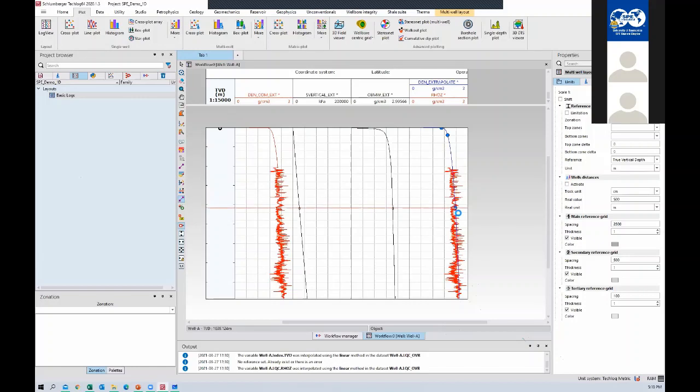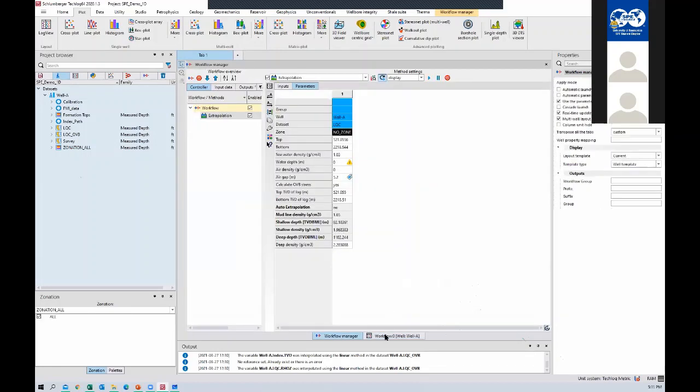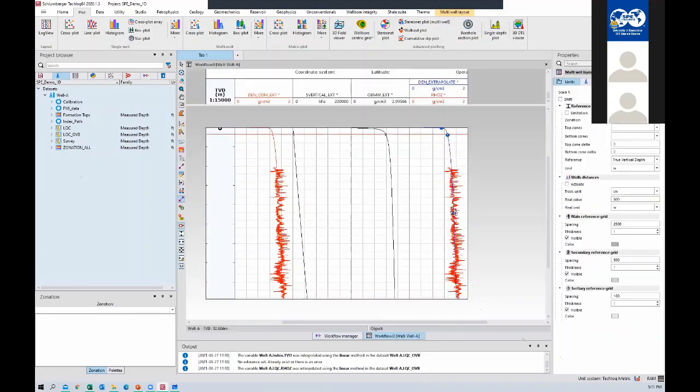Great. So that's how you estimate overburden stress. Once I finalize the parameters and know the trend, the blue line is showing you the trend. Once I am sure of the trend, why do I have to adjust the points? See the default. If you go with the default points, you might have a kink. Let's say you see a model like this. Let me zoom in. Why do I have to adjust the points?